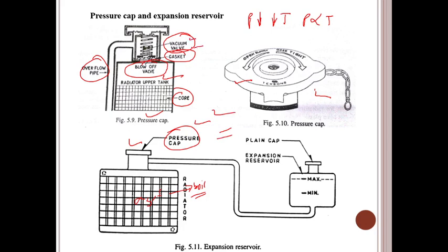When, due to severe working conditions, the coolant starts boiling and vaporizing, the pressure in the system exceeds a certain predetermined value, say 50 to 100 kilopascals. This pressure blow off valve is opened, releasing the excess pressure to the atmosphere through the overflow pipe from the system.